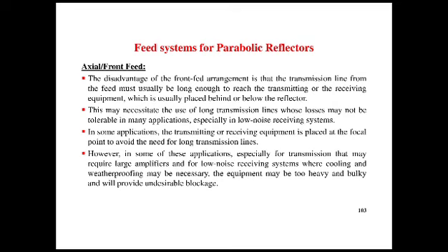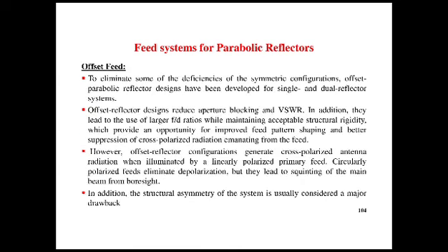So, feed for parabolic reflector. A disadvantage of the front end feed is that the transmission line feed must usually be long to reach the transmitting or receiving equipment provided by the reflector. However, in most applications, the transmitter or receiving equipment is placed at the focal point to avoid the need for long transmission lines.